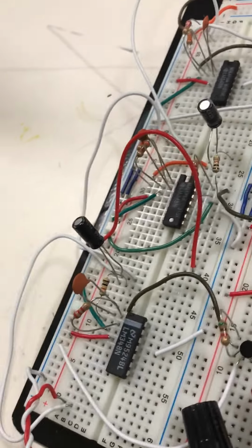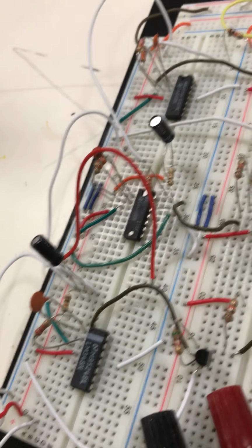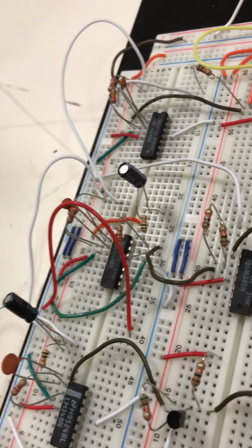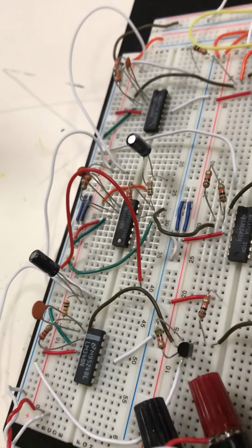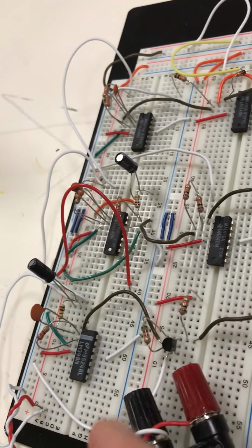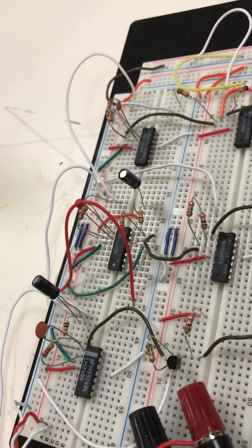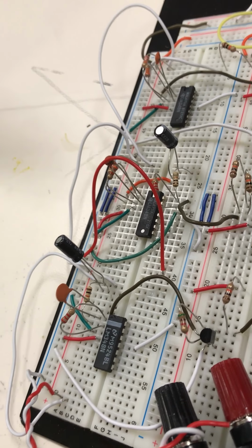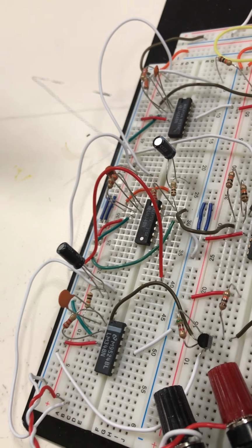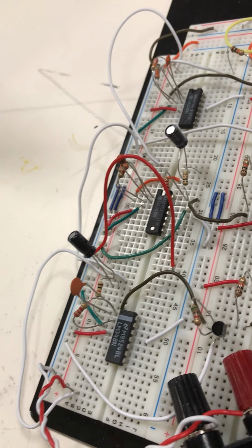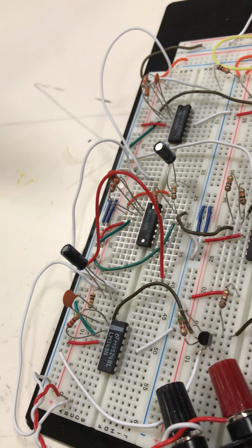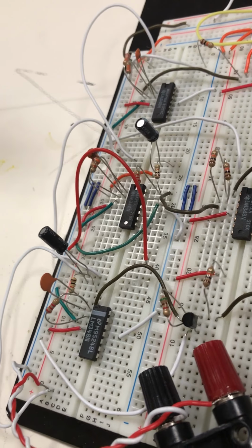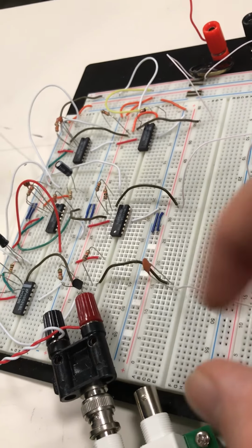And in the middle, we've combined the two into a bandpass filter. This is an active bandpass filter using the same resistor values. The 3 dB drop-offs for the bandpass filter will be the same as the high pass and the low pass, and the gain will be approximately 10 decibels. This way, this will have a selective range of frequencies where the signal will be allowed through, and the other range of frequencies will be attenuated and won't be able to be heard through the speaker. We're now going to look at the next 3 amplifier circuits.